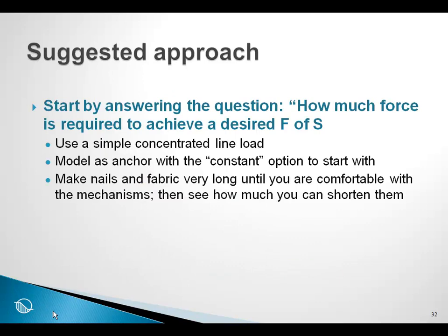So our suggested approach with reinforcing is that you start by answering the question: how much force is required to achieve a desired factor of safety? Use a simple concentrated line load if necessary, or model as an anchor with a constant option to start with, and make nails and fabrics very long until you are comfortable with the mechanism, then see how much you can shorten them. These are all techniques to help you answer this question.